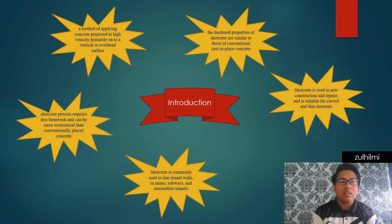Okay, now I will continue with the introduction. Shotcrete is a method of applying concrete projected at high velocity, primarily onto a vertical or overhead surface. The impact created by the application consolidates the concrete. Although the hardened properties of shotcrete are similar to those of conventional cast-in-place concrete, the nature of the placement process results in an excellent bond with most substrates and rapid or instant capabilities, particularly on complex forms or shapes.